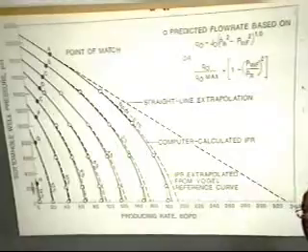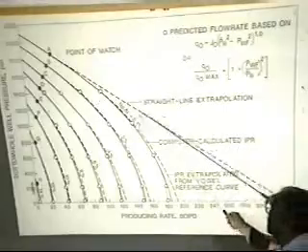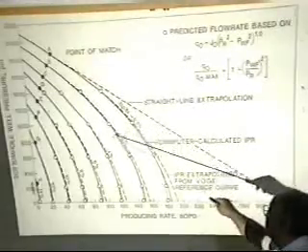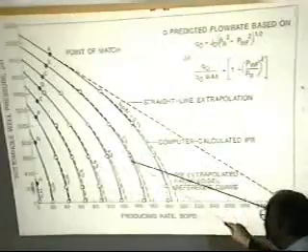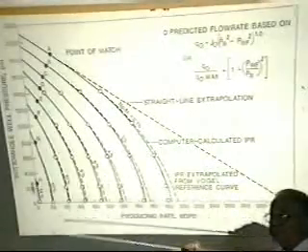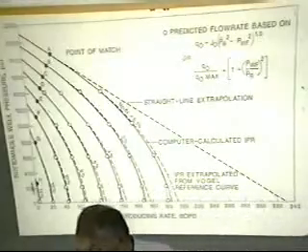So from a production engineering standpoint, there isn't much difference, but again, you also see that at different stages of depletion this curve continues to move. And again, the delta P squared fits all the way. It's a better representation of the inflow performance.